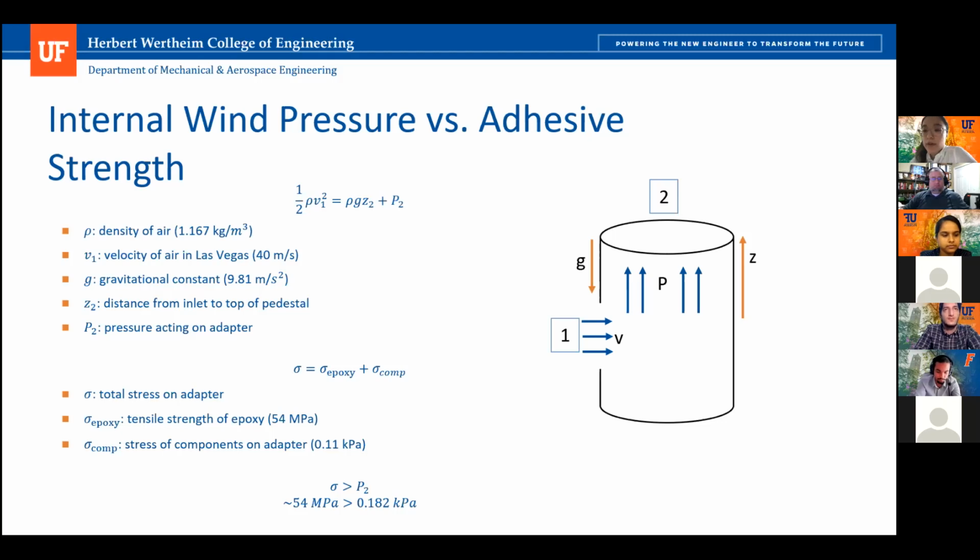We found that the corrosion resistance for galvanized steel with a relative humidity of 50% was about 34 years. So that's kind of how we justified our lifetime in that respect. Okay, was that out in the open? Because soil chemistry tends to do weird things with materials. This was a number cited from a study, so it was not, I believe, for a post underground. So that would be something we have to look into.